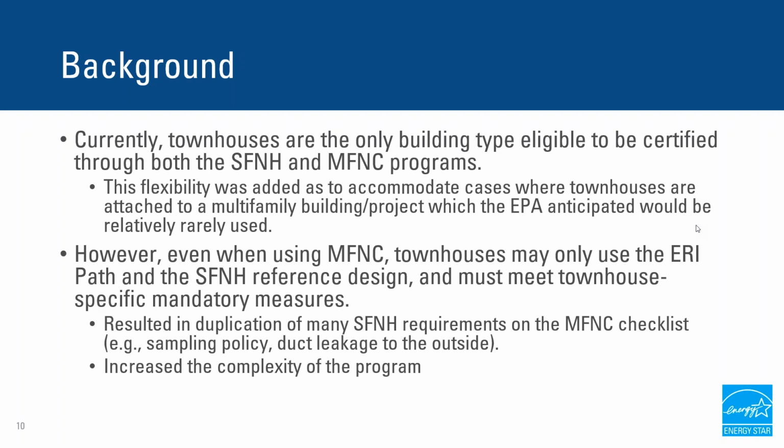However, even when using multifamily new construction, townhouses can only use the ERI path, and they still use the single family new homes reference design. In addition, they need to meet townhouse specific mandatory measures. So that meant that we had to add additional measures specific to townhouses on the multifamily checklist, duplicating them from the single family checklist.